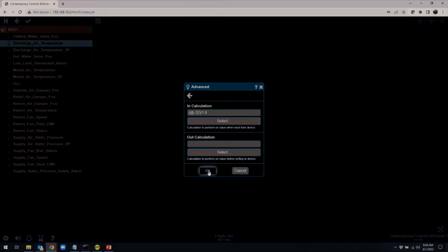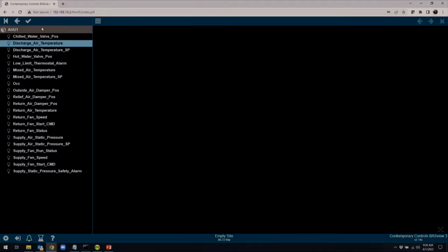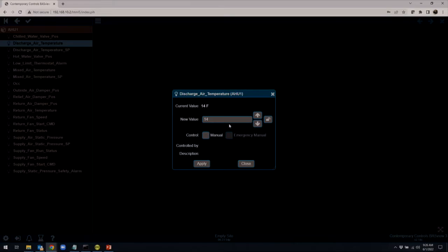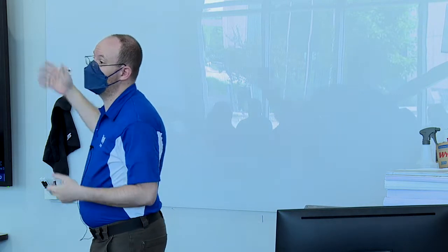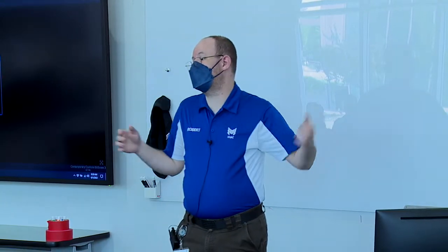What would that be used for? You will run into systems. If you get feet per minute, you want to do CFM. Exactly. You can take measurements and convert them to be more useful for you directly on a display. I've run into boilers that only gave me Celsius for the temperatures, and having to convert it to Fahrenheit, when it's built into the point, that's useful.